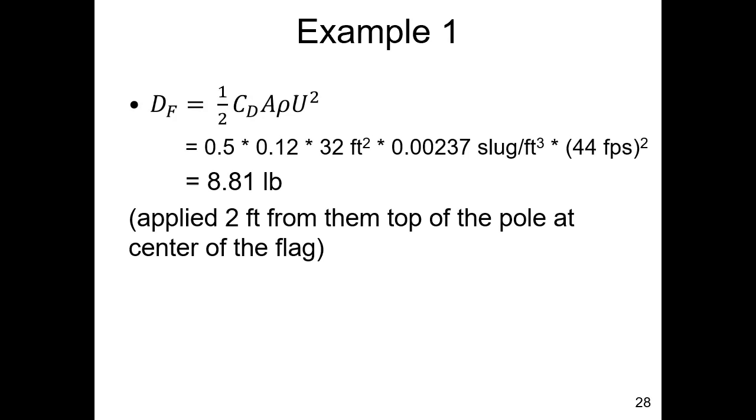So the height is 4 feet. So it acts halfway along the center line of the flag in the direction parallel to you. So it acts 2 feet from the top of the pole, or 18 feet from the bottom of the pole, 20 feet minus 2 feet.